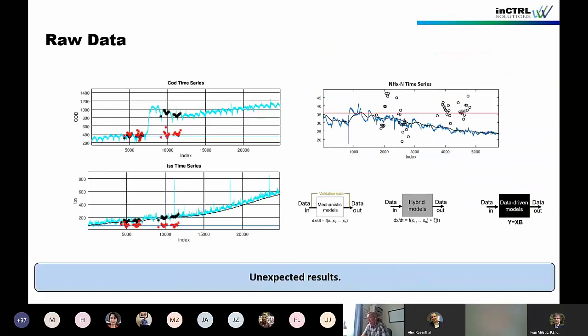Unfortunately, what came back was more than just a calibration issue, so not all the sensors. Basically, we had 2 tasks. One is making sure we understand the influent to all 3 sections, and then a specific task analyzing the hydrodynamics with very high resolution data. What came back is that mainly the influent measurements had not just a calibration issue, they also had a drift.